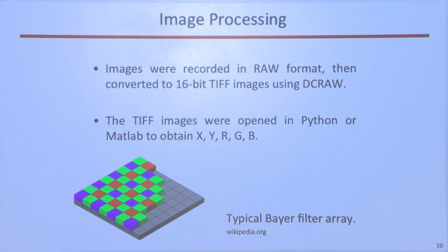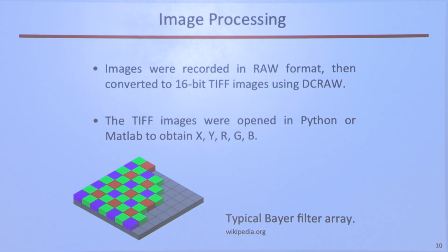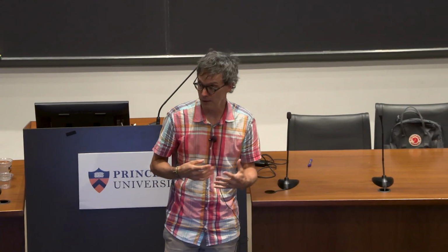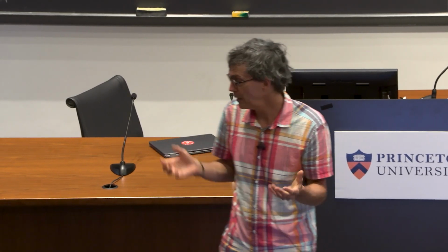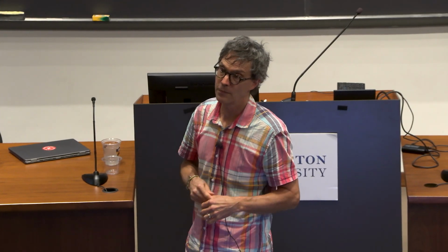You have to be careful how you open the images when you do the calibration. If you change anything, you just don't want to open this up in some kind of default application, because the default on computers is, of course, to make the dark things black and the white things white and adjust all the colors in between. And really with these kind of pyrometry measurements, any quantitative measurements with the digital camera, you want to turn off all the automatic features. Automatic gain, automatic focus, automatic shutter time, automatic ISO. They're made for automatic so that anybody can just pick it up and take a great picture, but you don't want that in the laboratory. And on the software side, the analysis side, and the down end, you don't want anything automatic either.